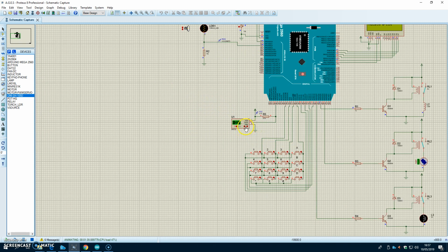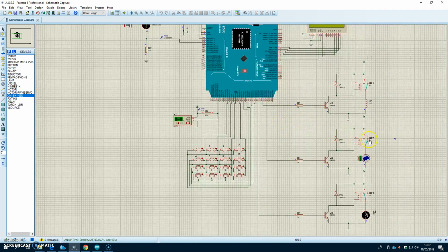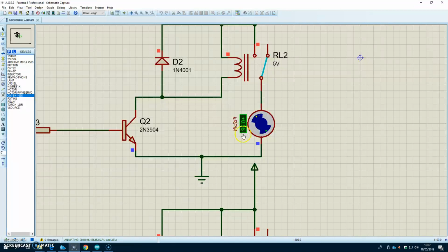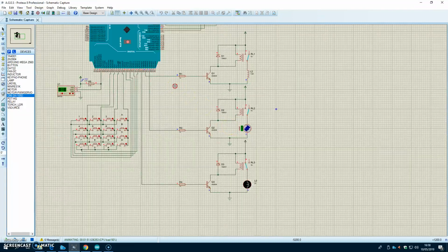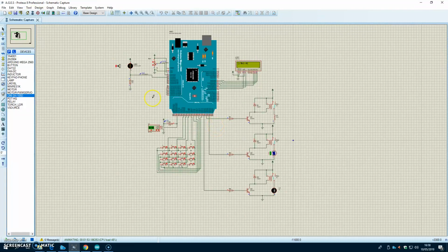So once again, if I drop the temperature below 40, see, the switch flips from on to off, stopping the fan. If you take a closer look, you can see the fan is slowing down. It'll be 0.55. There you are. So gradually the fan slows down on Proteus. However, in real life it should be immediate. And also the light. If I increase the light, it'll flip from on to off. As you can see, it's already done.